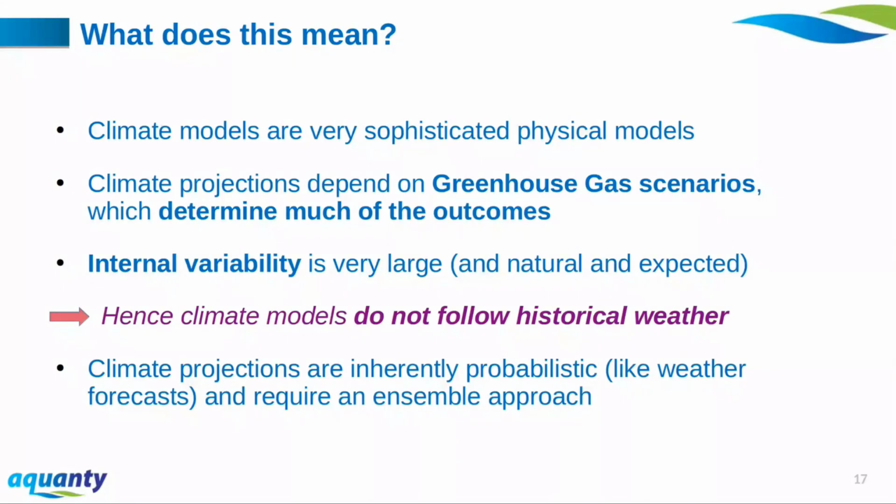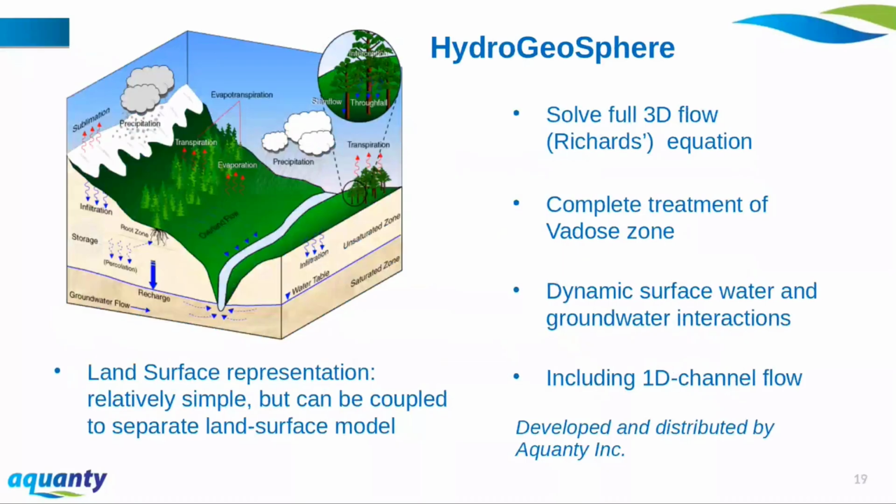So now to HydroGeoSphere. I'm assuming a lot of you probably are aware of HydroGeoSphere, but if you're not, I'll just briefly say, HydroGeoSphere is a surface-subsurface integrated hydrological model. Essentially, it solves the fluid dynamics of the 2D surface and the 3D subsurface. It solves the full 3D Richards equation in the subsurface, unsaturated as well.